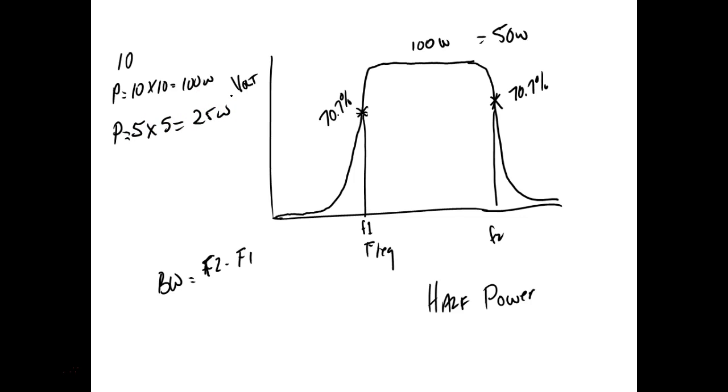Power varies with the square of the voltage. So if the voltage goes down 1/2, the power is going to go down 1/4. If it goes up, it's with the square. If it goes down, it's the reciprocal of the square. Because voltage and current are directly proportional. I could put this on a test. I could teach this, and then I could come back and put it on a test and somebody would say 5 volts. So don't feel bad. I expected that.